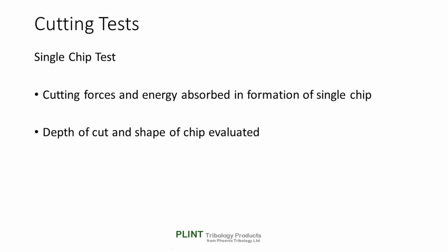An advantage of this type of simple test configuration is that the test tool itself may be preheated out of contact with the machining fluid in the bath before the pendulum is released. This allows tool temperatures substantially above the fluid temperature and thus facilitates tests with slurries.